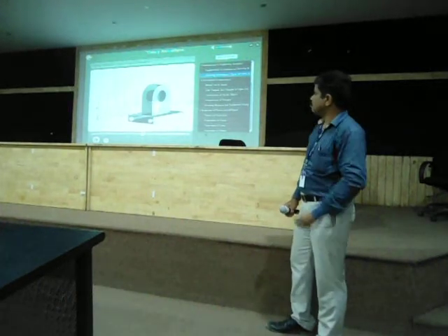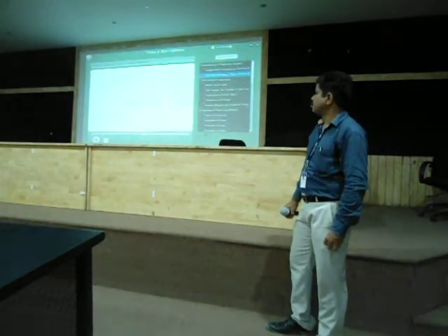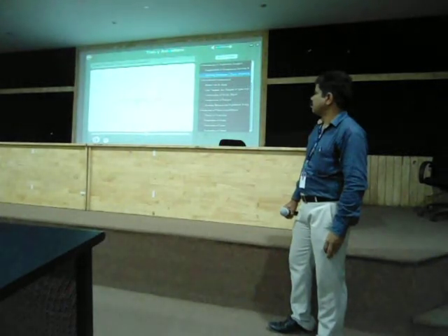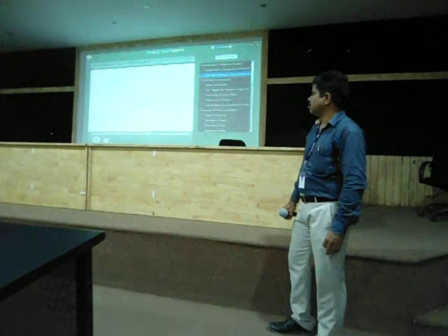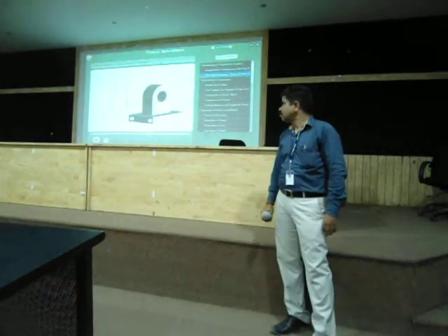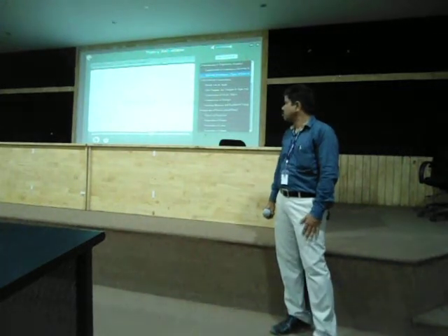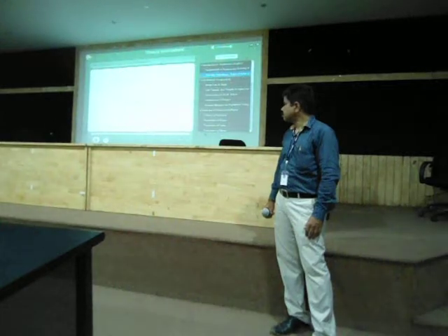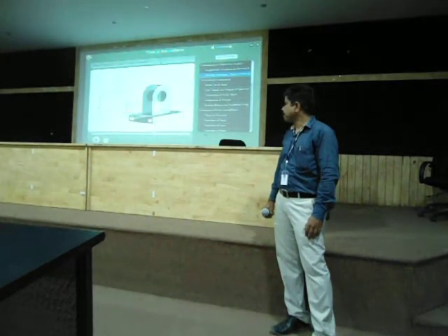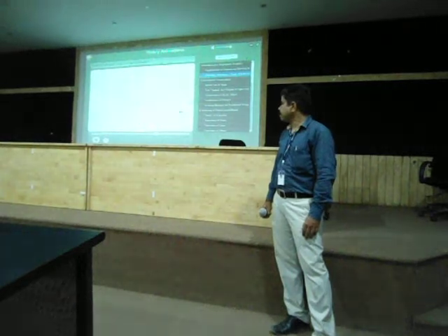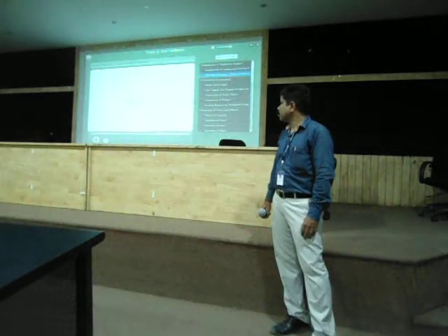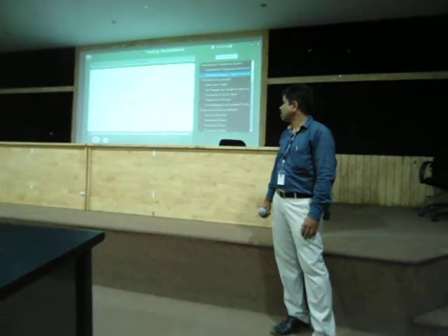Various types of lines are used to represent different entities, like visible lines are used for drawing outlines of visible edges, and surface lines which represent the objects. These are drawn in bold, dark, and continuous lines. Hidden lines are shown with medium thin lines consisting of short dashes and are used to represent invisible edges and surface boundaries. Center lines are thin lines drawn with alternate long dashes and dots and are used for representing symmetrical objects. Then there are dimension lines, extension lines, and cutting plane lines.